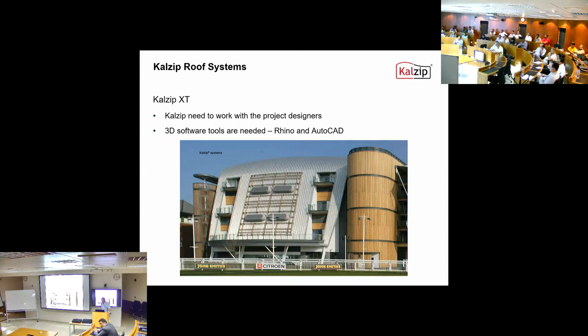So in principle, you don't have any dropping joints on the system, all welded. So the joint sheet to sheet has to be welded, right? Or could be lapped. We do a step detail, so the step detail is one sheet slightly above the other, so they're separate and one can move independently of the other sheet. That's one way of achieving it, or we can weld them together. Sometimes, depending on the roof pitch, if it's quite a steep roof pitch, we can just lap the sheets and rivet them together with a mastic strip between the sheets. So different options we can achieve.